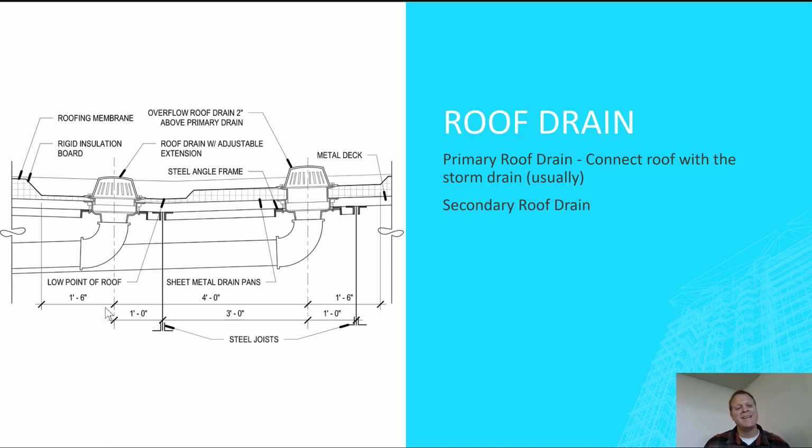You get a big disturbed area that you had all prepped and ready for concrete because we didn't have these things connected yet. So super critical: as soon as you get these things done, have the plumber right there, have the plumbing piping all ready so they just have to make this connection.